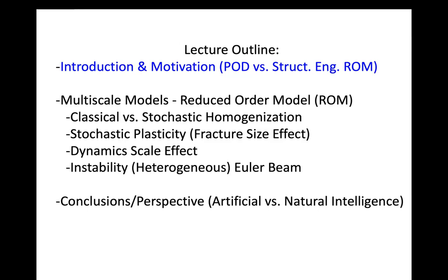Because if your structure is twice or three times as big as your specimen, and it's built on composite material, there's something called the size effect: the failure modes might not necessarily be the same as the failure modes of this small specimen, simply because the heterogeneity in the large structure might be much more important, and the fracture being sensitive to the initial or induced defects, you start fracture sooner. So the bigger the structure, the more likely it is that you have a fracture sooner. And that's certainly not good news, because testing then does not give you the safety.